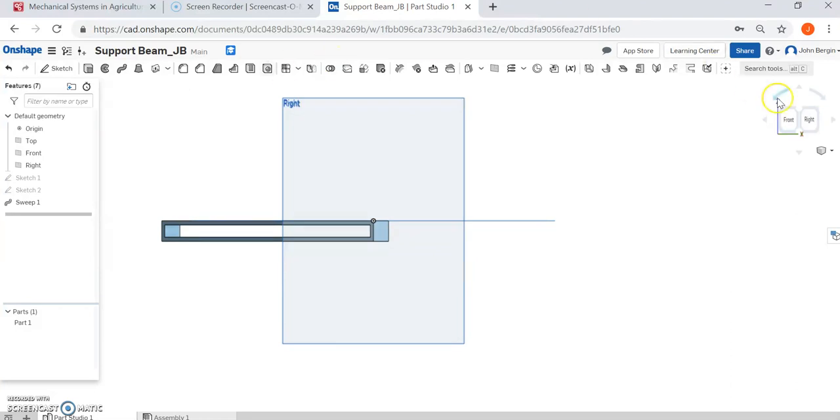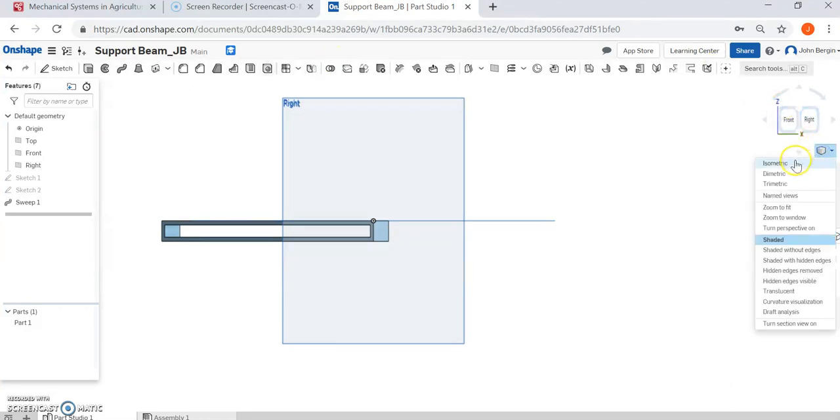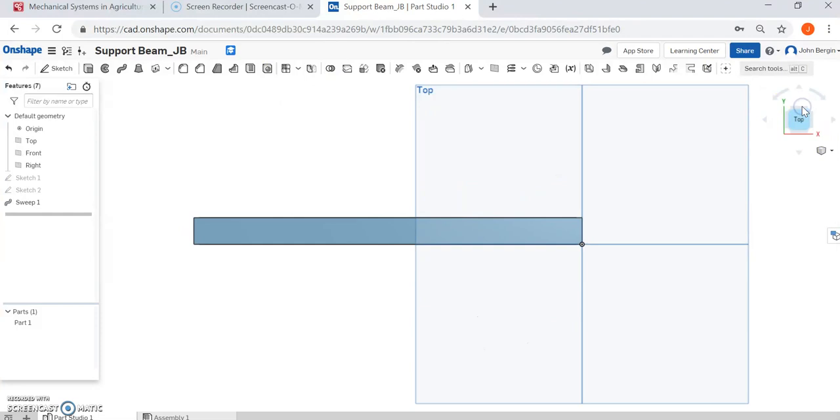So next we're going to go to the top view, and we're going to sketch out 3 points on top here, and then we're using a different toolpath, linear toolpath, and then we're going to extrude down so that way we have our support bars for a beam.